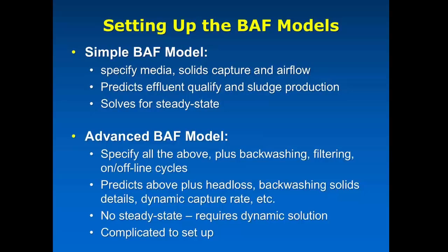It also predicts things like the actual dynamic removal of the solids and how much head loss do we have as that filter fills up and so on. Because of all of that, it's not really a steady state system. There's always something turning on and off or backwashing starting and so on. And therefore, you can't solve it for steady state. You have to run a dynamic simulation for a period of time to be able to come to some sort of convergence of an answer.